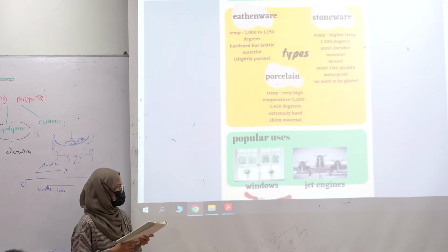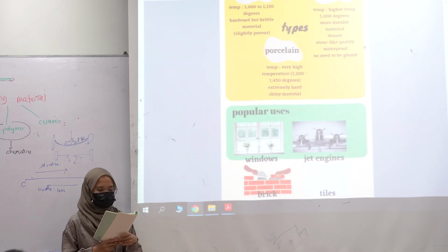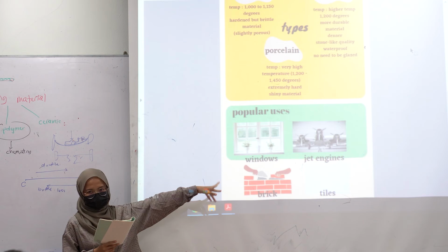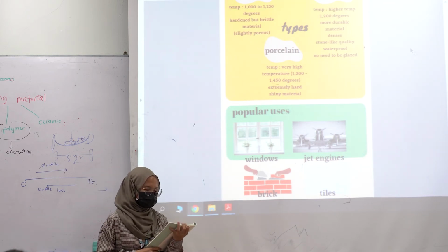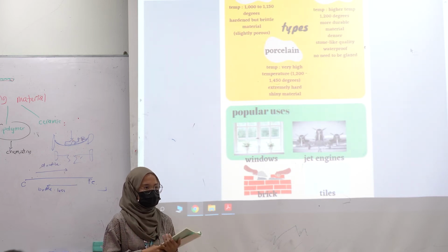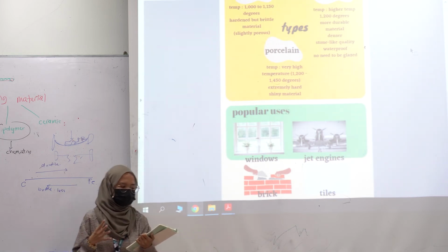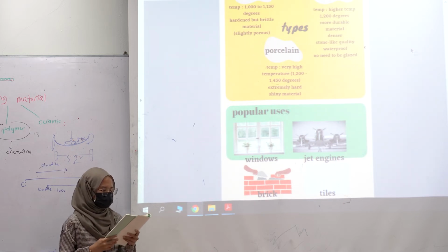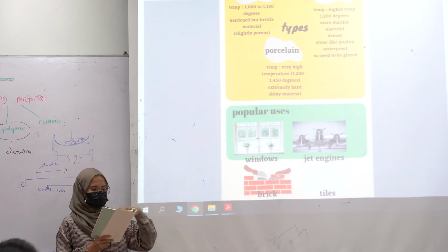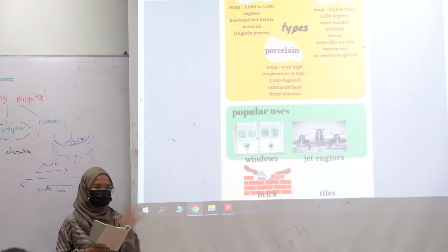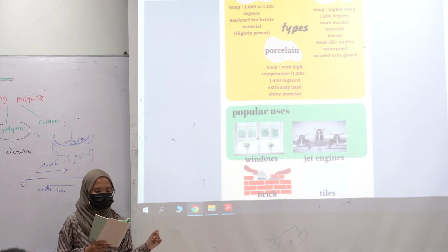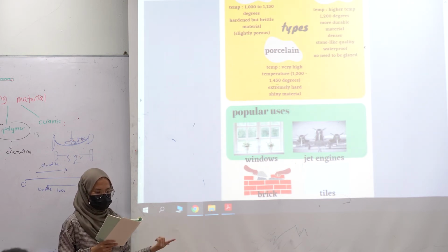So next is the advanced ceramic, but that one I didn't explain in the slide. Okay. So advanced ceramic is more of a product made from inorganic, high purity compounds through a series of specialized manufacturing processes. So the difference between advanced ceramic and the traditional ceramics is these advanced ceramics are not generally clay-based, and they are based on oxides and also non-oxides.